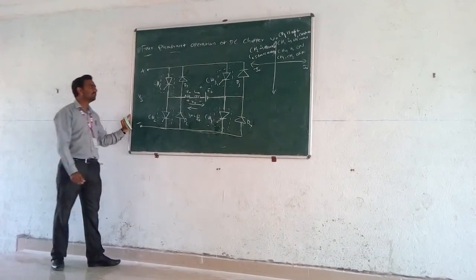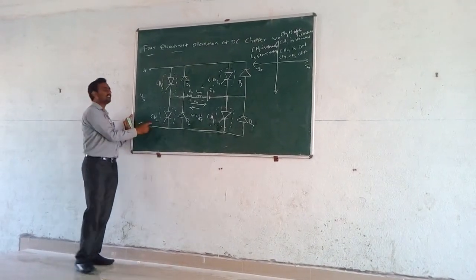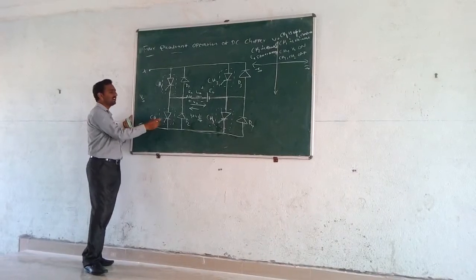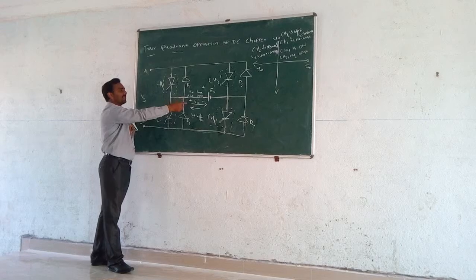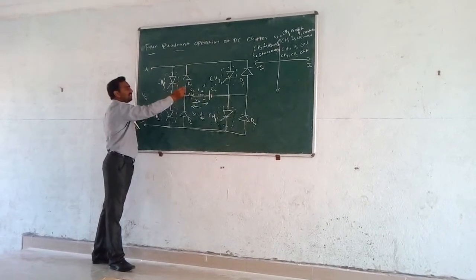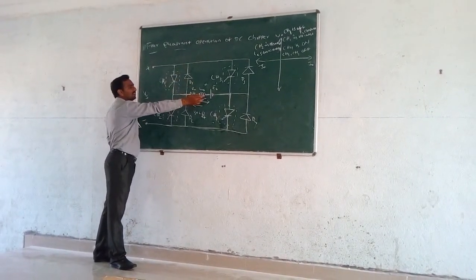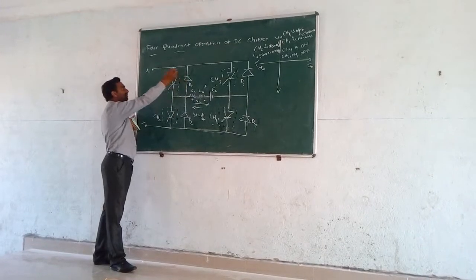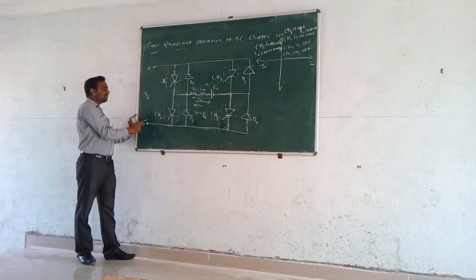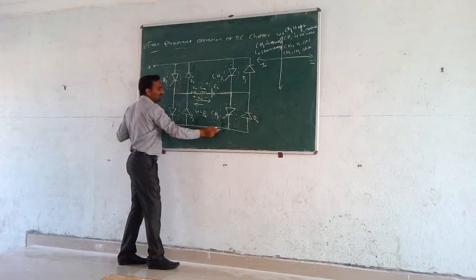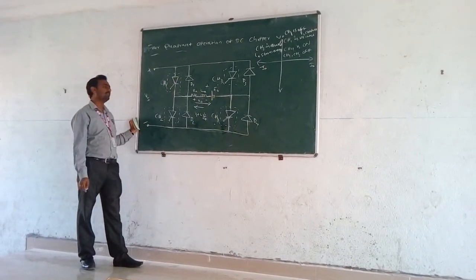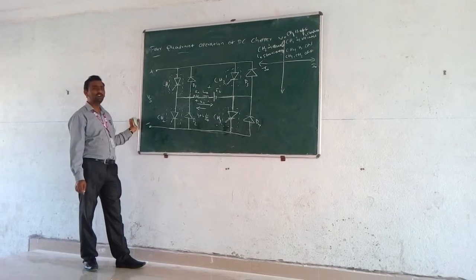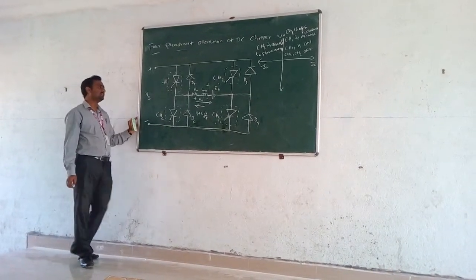When CH2 is off, the voltage across the output is greater than the supply voltage. At that time diode D1 starts conducting and the current flows from EB, LA, RA to D1 to the positive supply, then the negative terminal of the supply, and through D4 returns back to the back EMF. This is the second quadrant operation of the chopper.